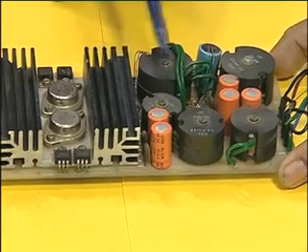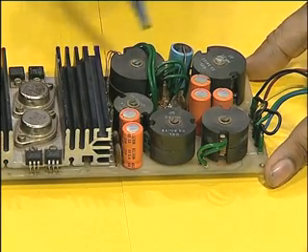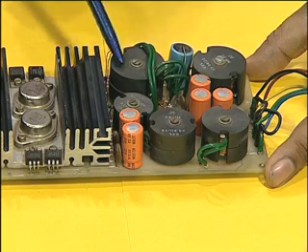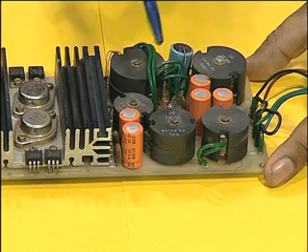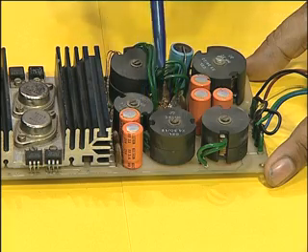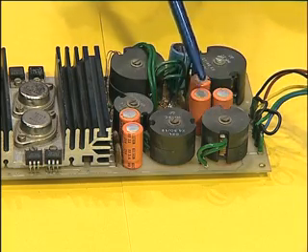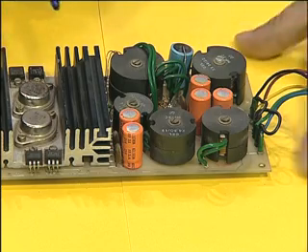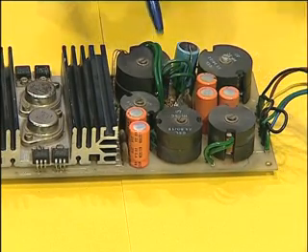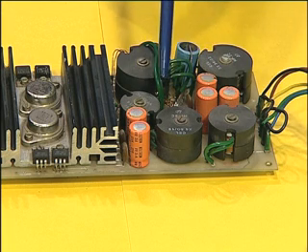and then gradually if I move this board here, what comes into focus are some pot cores. This pot core is used as a transformer. These pot cores are used as inductors. Again, some electrolytic capacitors for the output. The pot cores here are the ferrite pot cores, and they are normally for high frequency applications.